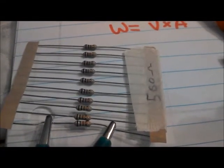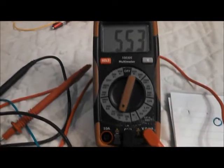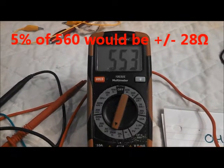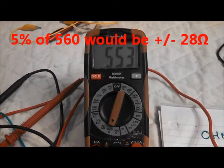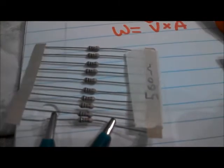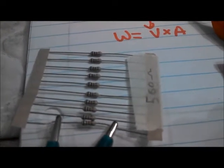It's labeled as 560 ohms, and as the meter shows, it's within the 5% tolerance. It's reading 553 ohms. That is a lot to take in, but basically it's reading 560 ohms nominally on a quarter-watt resistor.